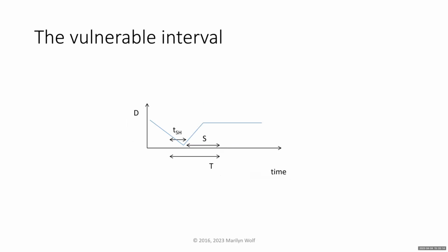We have some value we're setting up at the D input to the register. We expect that that input value will be presented to the input of the register for some amount of time before we actually set the clock level. Let's call that the setup and hold time, or TSH.